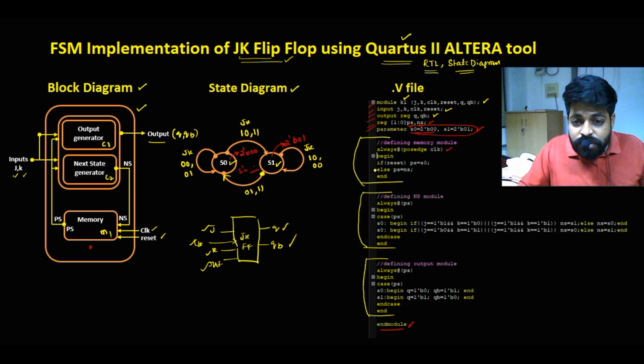So what I am trying to do is define the memory module M1 over here. This is my definition for the memory module, the procedure block: always @(posedge clock). In between I have all the statements, right? In the same way I will have combinational circuit 2, which generates the next state. Its procedure will be defined in the C2 block, and here is my C1 block. So the always statements I have to write three times: M1 module once, C2 module once, and C1 module once.